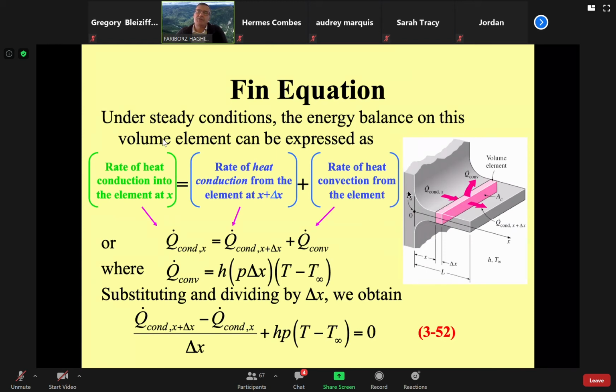The temperature here is almost, we assume, T0, and then slowly passes through this part. Usually the fins are made of very high conductivity material, such as copper, because you would like to encourage heat transfer from here. As heat transfers through here, there are losses by convection to the outside.